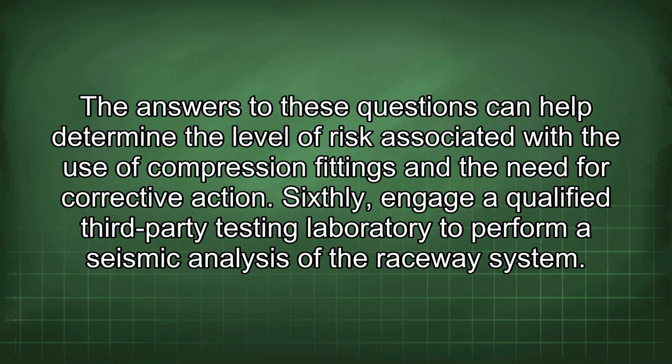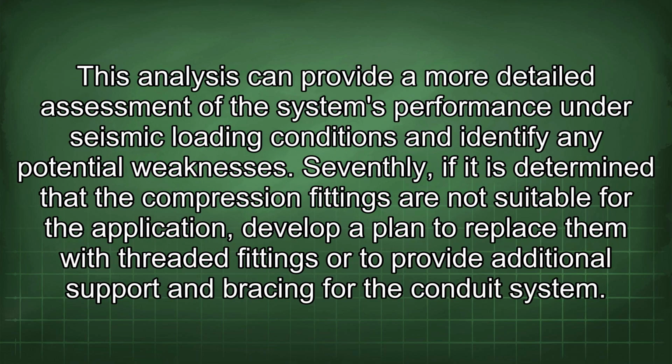The answers to these questions can help determine the level of risk associated with the use of compression fittings and the need for corrective action. Sixthly, engage a qualified third-party testing laboratory to perform a seismic analysis of the raceway system. This analysis can provide a more detailed assessment of the system's performance under seismic loading conditions and identify any potential